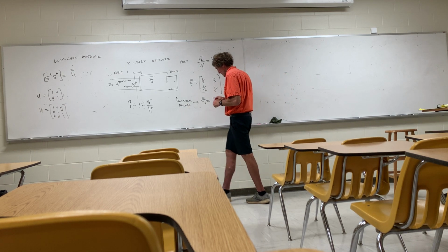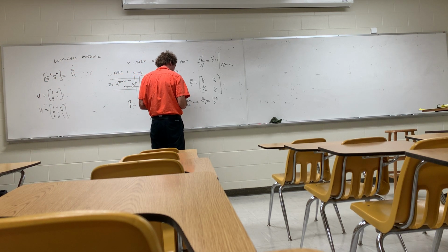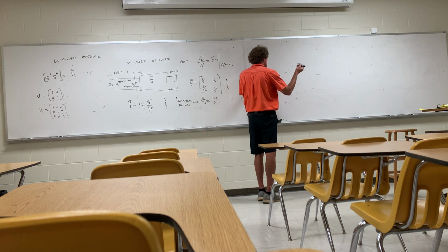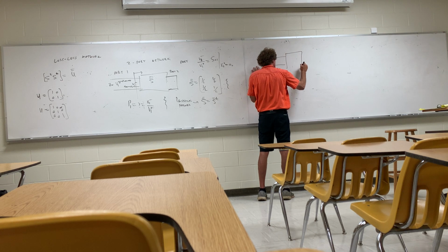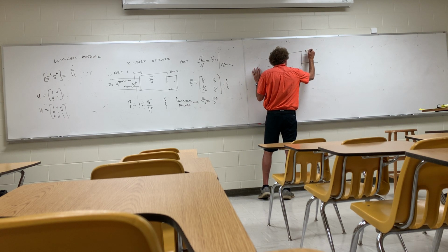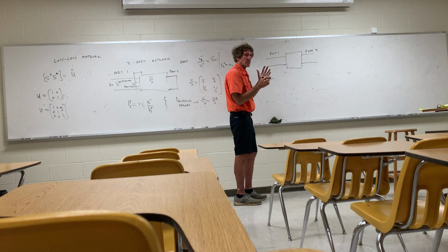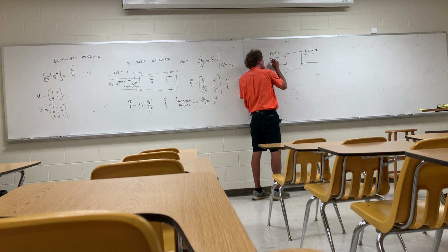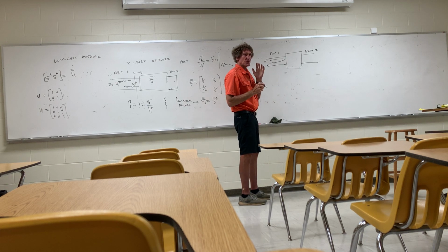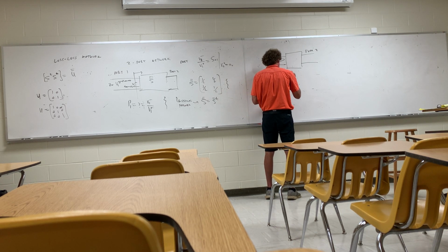So, if you have a system like so, port 1, port 2, and you talk about a return loss. I want you to think about this naturally. Return would be something, you send a signal in and it comes back. This would be V1 plus going in, this would be V1 minus coming out. So the return loss, or RL, is equal to minus 20 times the log of the magnitude.